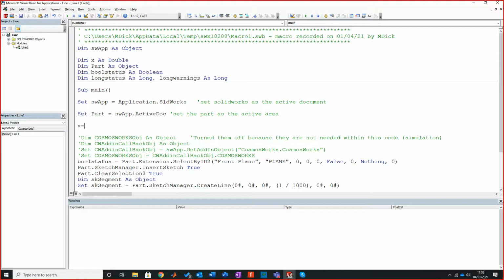So what I'll do first is say x is equal to input box. Now input box is a direct command. All this, by the way, is in the notes that's attached. So I'm going to input box, open bracket. Now when I go input box, it literally says enter a prompt. No quotation, and I will go enter line length. Define it as millimeters. Close that.